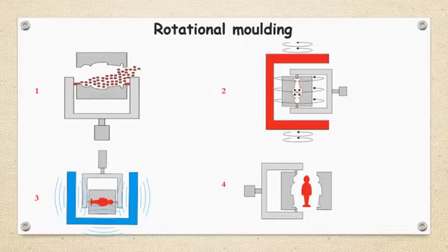During that process, the powder poured inside the cavity gets heated, expands due to the rotation, and attaches to the mold cavity boundaries as a very thin layer. The smoothness or layer finishing will depend on the finish of the mold cavity. Here the actual finishing depends on the mold cavity finish. You can get very high quality smoothness on these components as well.